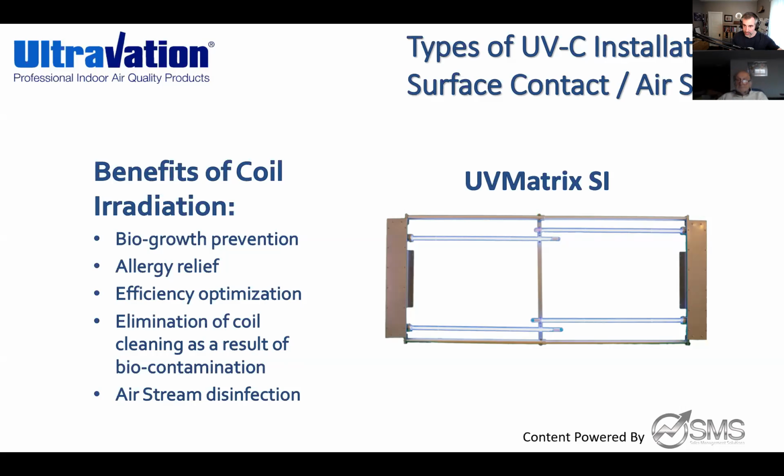We also can adjust the placement. Some people are fine having a 20-inch gap between the bulbs. I know from the engineer's design, he prefers to have an 18-inch or less space between the bulb spacing. So we can move these around in our designs to make sure you're getting maximum potency on that coil application. So this is all options available to you guys. And then again, this could be dealing with surface area contact, but also since the air is blowing through the equipment, you are gaining some airstream disinfection as well because the UV is shining 24/7.